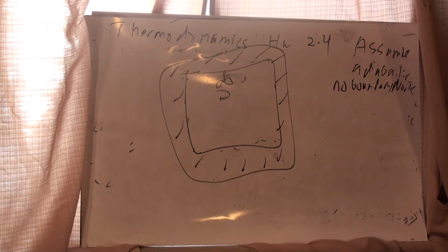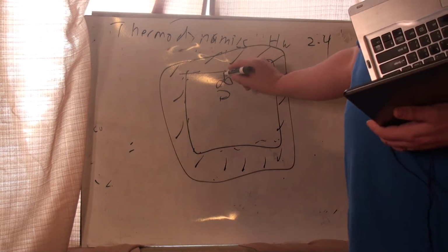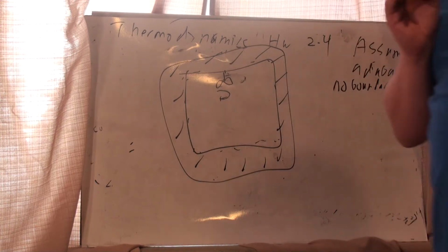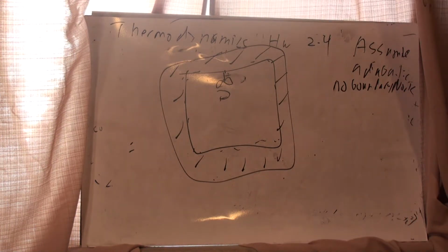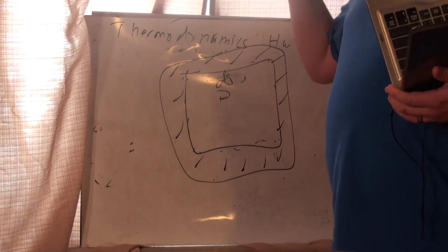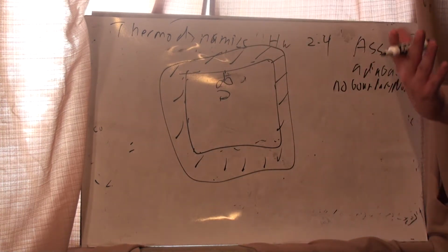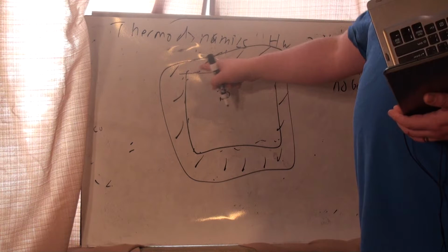Do we have shaft work? Do we have things spinning? Okay, that's a good question. We do have something spinning, but where is it spinning? It's spinning the motor. If you ever look at a ceiling fan, the motor is not in the wall. It's on the fan. So yes, there is work being done, but it's being done within the boundary.